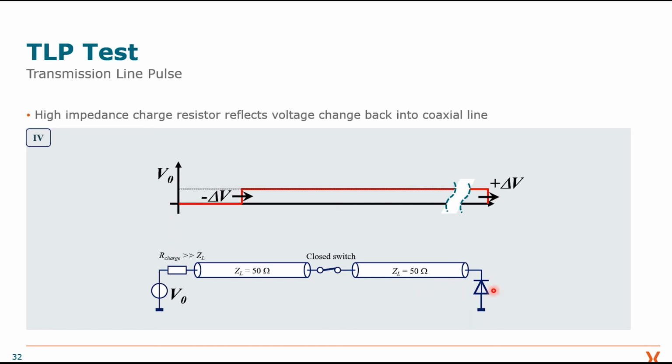And what you do here is measure the voltage at your diode, and also the current which is flowing through the diode. So we have a very controlled, impedance controlled system here, and possible reflections which are present in ESD are avoided by using this setup.